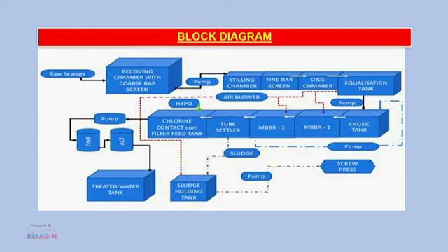Then stage 10, the biological decomposition tank, that is the MBBR tank, moving bed bioreactor. The sewage decomposes the biological impurities with the help of aerobic bacterial culture on special media in the presence of air in the MBBR reactor. Two are provided in series. The required air will be provided with the help of an air blower and a coarse bubble air diffusion grid.